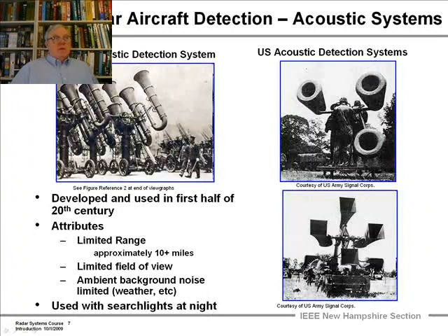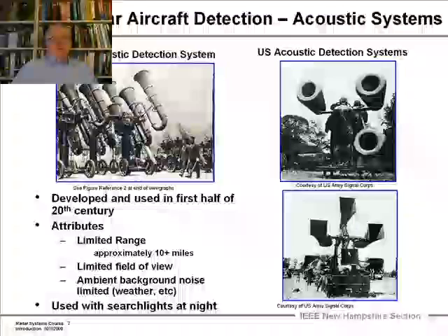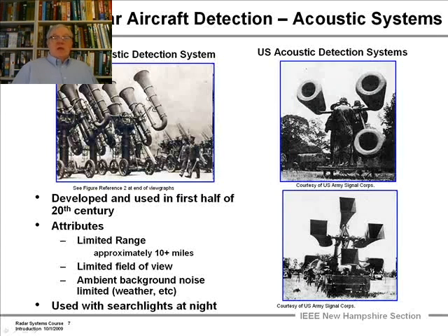You notice, particularly in these systems, there was an antenna listening above and below, and an operator with earphones measuring if this signal was higher than that signal. They knew that they weren't pointing exactly at the angle of the planes, and so they could adjust on azimuth or elevation the instrument and get the right directionality of where the aircraft or group of aircraft were coming from.